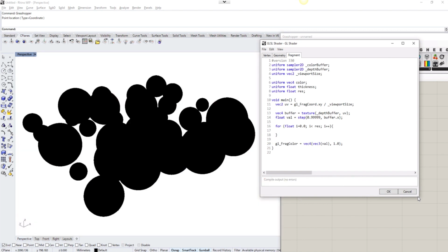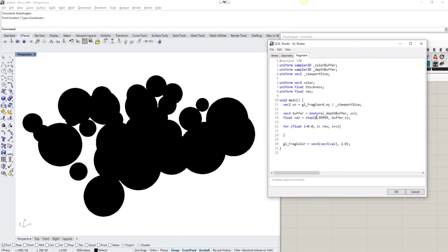Now let's also calculate the step angle depending on the resolution. I want to make a direction like 360 degrees divided by resolution for a step angle. So if the resolution is 4, then 360 degrees divided by 4 becomes 90, and if you have 4 rotations of 90 degrees, you'll get every corner covered for 360.